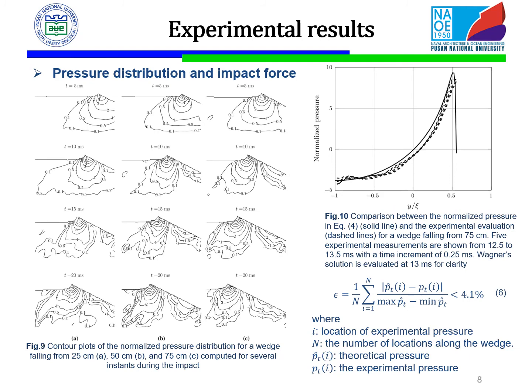Figure 9 displays the indirectly measured pressure field for the free falling height computed for several instants during the impact. The experimental results demonstrate that the peak pressure is located where the water piles up on the wedge. From the location of the peak values, the pressure sharply reduces in every direction with a trend that is almost inversely proportional to the distance from the peak location, and is null at the free surface.